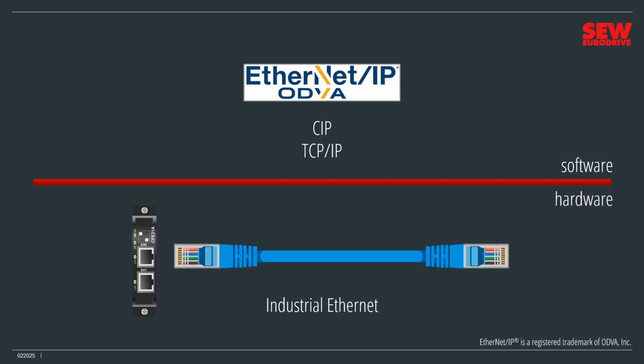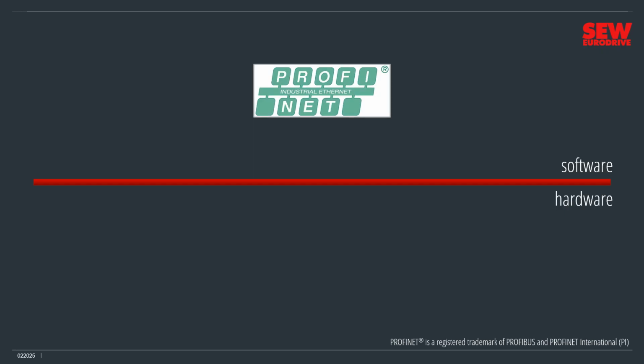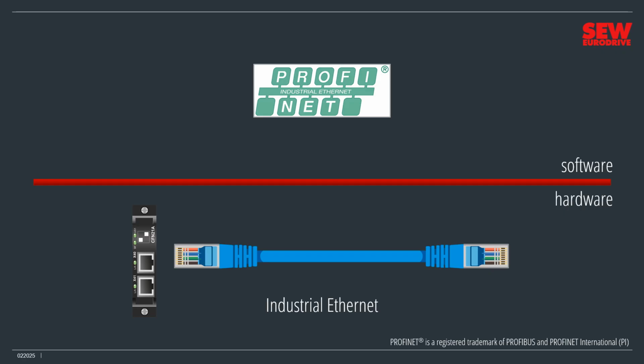The third example is Profinet, which is very popular in Siemens systems. It uses industrial Ethernet for its hardware side. The software side is a bit unusual, however. One side handles communication that isn't time critical. It has two parts, TCP/IP and Profinet (NRT). The other side has just one protocol component called Profinet RT, which stands for real time. By having less software overhead, this side can communicate more rapidly and predictably.